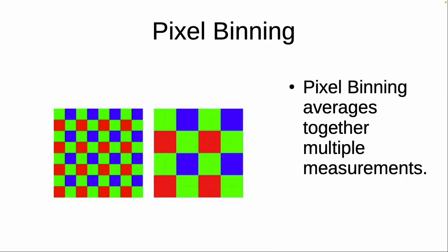But these cameras have so many pixels, right? My desktop monitor has what, 1.5 megapixels or so, and you can easily get 5 or 12 megapixel cameras. So what makes much more sense is to do pixel binning, and then you get some averaging, which reduces the noise. And so you can bin horizontally or vertically, but typically you bin by a factor of 2 in each direction, so you get a quarter as many pixels out. Great. That reduces your bandwidth, so that's good too.